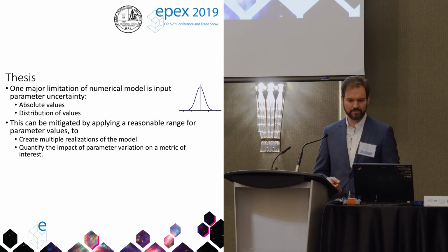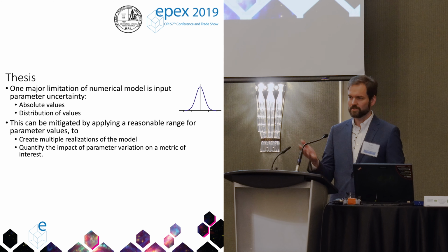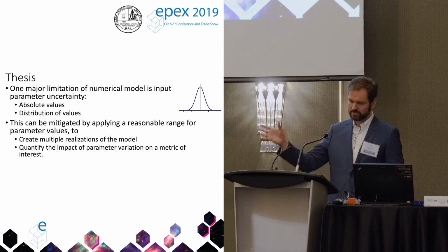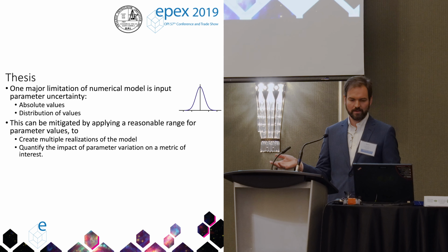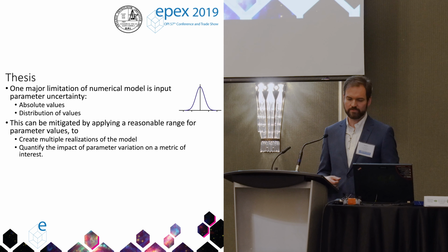So for instance, in Southern Ontario, maybe you're looking at one reservoir and you've got just one measurement of geomechanical properties for the A2 anhydrite cap rock. But over many pools, you might have many measurements. So this type of information you could then use to estimate a reasonable distribution of properties for that particular unit and other units. And you can then sample from this distribution to create multiple realizations or versions of reality, which you can then run in your model